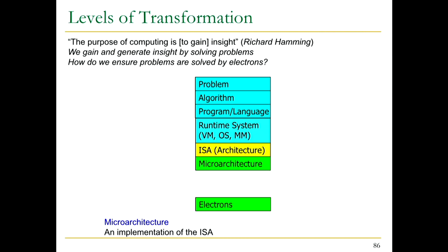You can say, I'm going to compute both outcomes: an outcome assuming that the previous bit is 1, and an outcome assuming that the previous bit is 0. You design hardware to do both. And then when you really know the outcome of bit 0, you select the right answer. So that's one method of parallelization, right? And you do it for every bit. Of course your adder becomes huge because it's a dependence chain, but that's how you can do this addition in parallel. Now I've given you just 2 implementations of an adder, bit serial versus this hugely parallel, complicated adder.